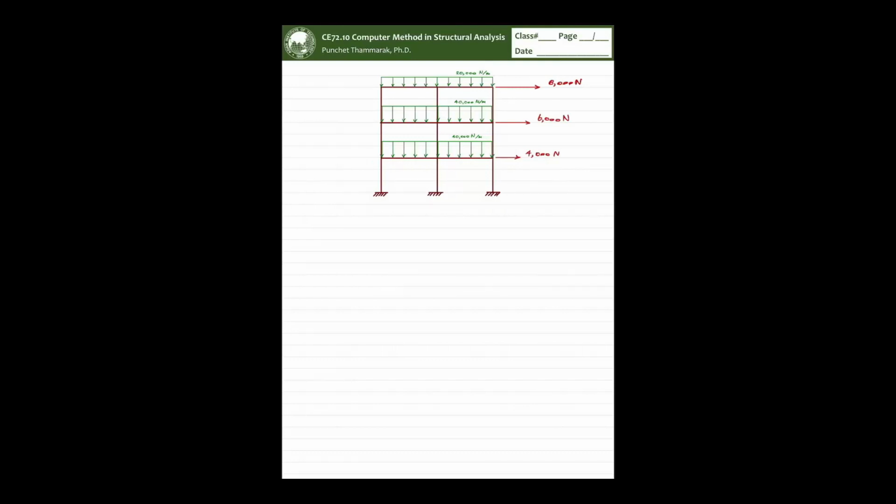It combines all the loads. Make something simple like a cantilever beam, a cantilever column, or maybe just a one-bay frame, and then you know that if you apply load like this, it's going to behave, it's going to displace like this. You are able to perform the hand calculation to check. Maybe you perform an Excel calculation to check if you get something that matches what we learned in the class. And if you don't get that from the program, find out what goes wrong. Maybe it doesn't go wrong, but it might not be going in the same way that you think.